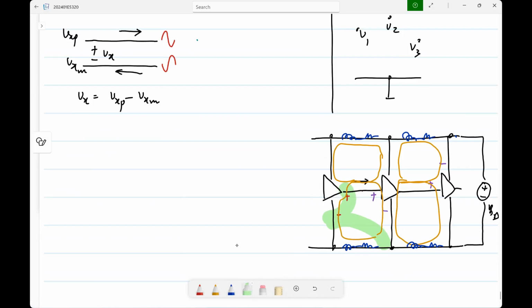And it may not always be easy to predict how much drop you will get there and so on. Because the actual current flowing through the supply rails is not only because of this stage, it could be because of other stages, many things that are connected together. And exactly how the current splits is also not always clear. For instance, it could be that if the current output here is a sinusoid, the current drawn here is a sinusoid.